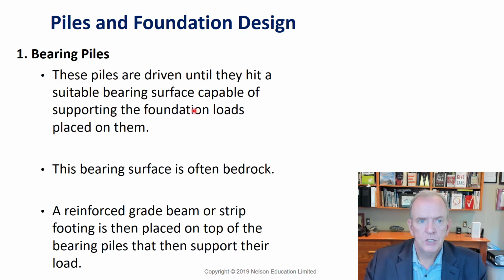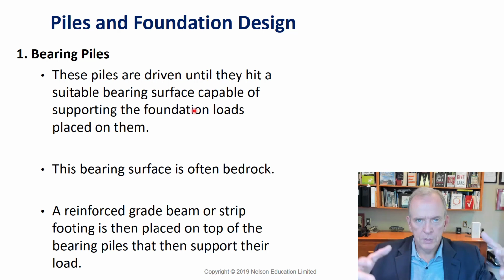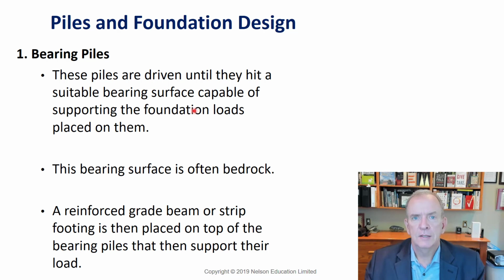So piles and foundation design. We talked about soils having the proper bearing capacity. Well, in some cases it doesn't have the proper bearing capacity, and so in cases like that we have to find ways to support the foundation. And one of the ways that we use are piles and bearing piles. Bearing piles basically could be wood, it could be concrete, it could be steel that's driven down into the ground until it hits generally bedrock that it can support the actual weight of whatever the structure is.